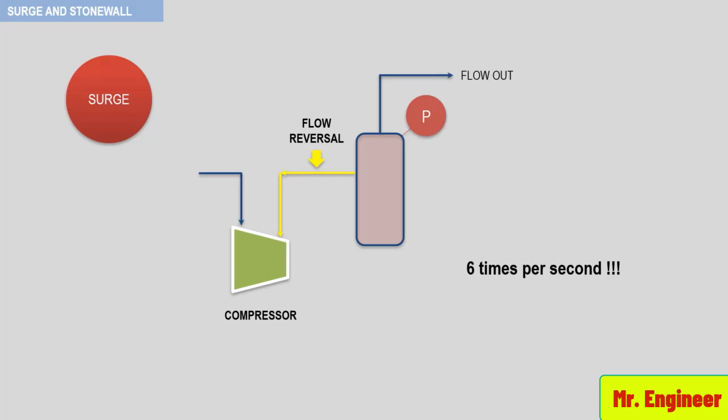This phenomenon can occur most easily in axial compressors. Therefore, surge is to be avoided most in axial machines due to their ability to heat up faster than centrifugals, and also as a result of the blade configuration, which can be more readily excited than centrifugals.